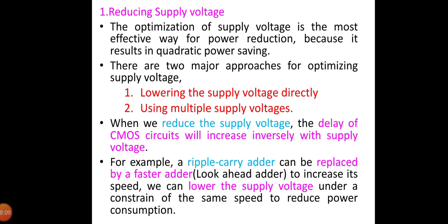Parallelism is not the only way to compensate for the loss in performance. Other architectural approaches, such as the use of pipelining, can also be employed for the same goal. The most important message in the preceding analysis is that if power dissipation is the prime concern, dropping the supply voltage is the most effective means to achieve the goal. The subsequent loss in performance can be compensated, if necessary, by an increase in area within certain bounds. This is acceptable since area is no longer the compelling issue, due to the dramatic increase in integration levels.